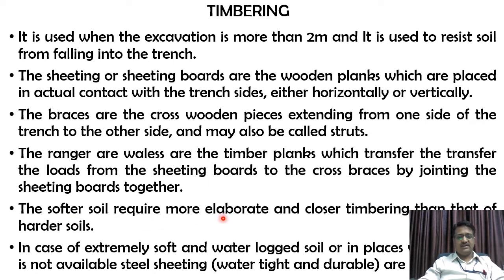The soft soil requires more elaborate and closer timbering than that of the harder soils. That is quite obvious. If it is hard soil, then it has the capacity to hold itself and not let soil cave inside that particular trench. But for a softer soil, we need to have much closer spacing of these timbers for safety purposes.